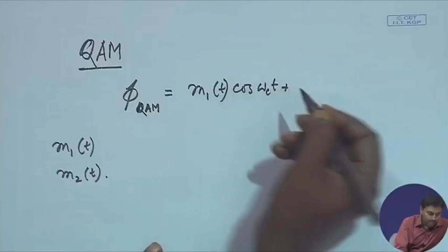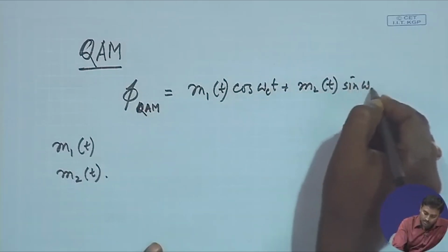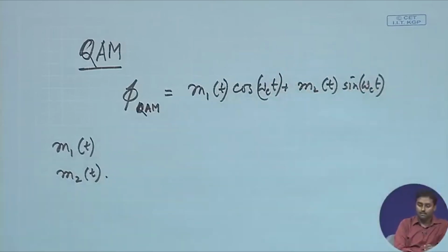So, they are similar signals. They might have different spectra, different time domain representation, but the overall band that is being considered for them is similar. As long as that is happening, I can represent them as this composite signal. So, it should be m1(t) cos ωct plus m2(t) sin ωct. That is exactly what we are trying to achieve.